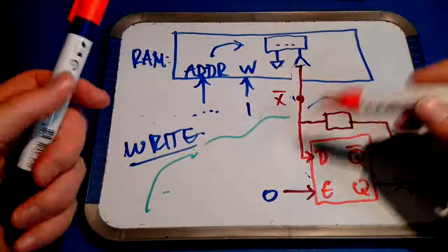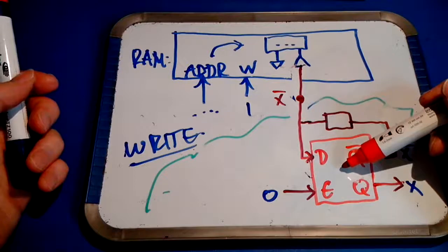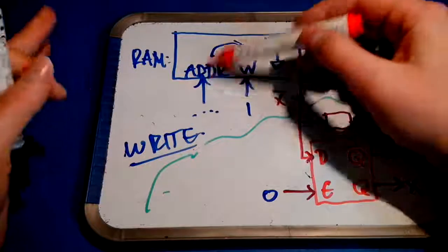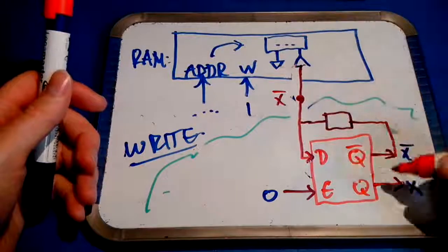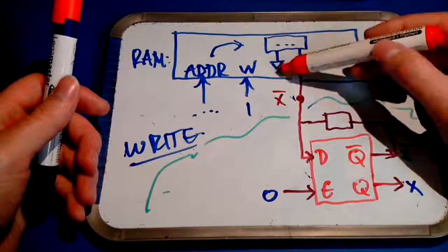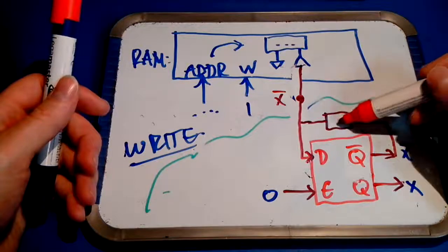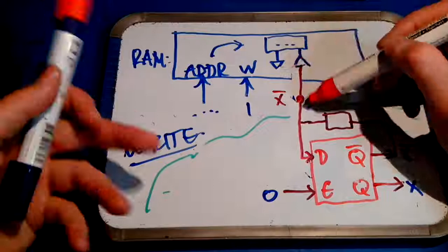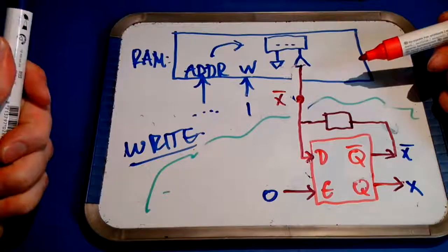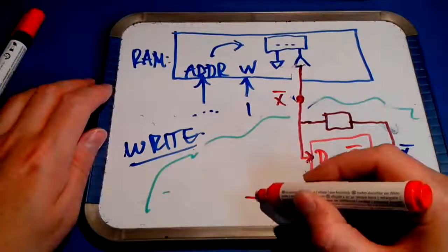So the operation of the CPU, for details please see another video, is first the D latch reads a value from the RAM. It doesn't matter which address, someone else addresses the RAM, latches it, so the Q output becomes the original value. Then it will enable the write input of the RAM, thereby disconnecting its driver, so that this weak signal, weakly coupled by this resistor into this node, will drive this node, and then the RAM will see this value. So that's basically how it works. Now in the context of the whole CPU, this signal will eventually come from a clock line.